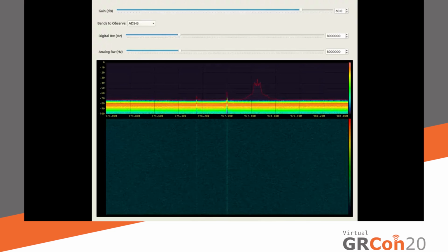Together, all these generated signals, the pulsed radar, analog voice, and ADS-B, could be the basis of an RF test environment for SDR algorithms. The signals we have chosen span several different bands, but a user could certainly generate a more useful RF environment that would focus on a single band.